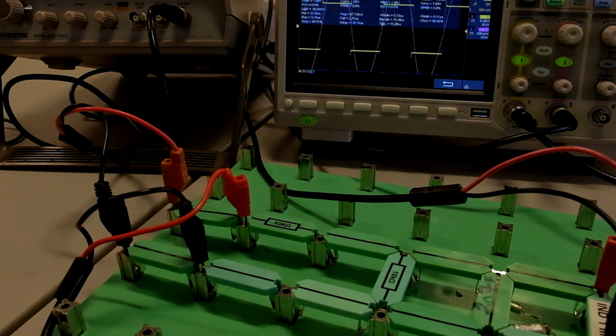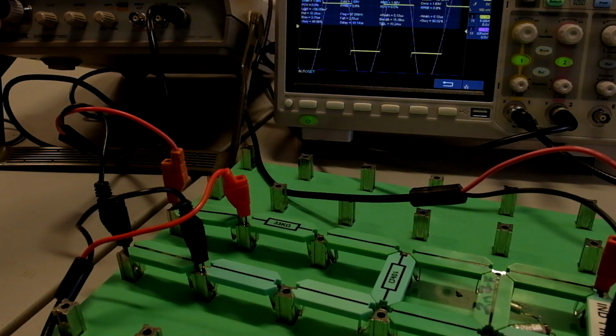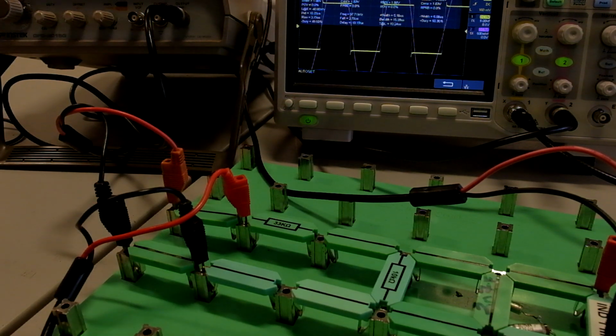So if we go to resonance, although we have a square wave going in, it filters out all the higher frequency components of that square wave, and we only get a sine wave coming out at resonance. If we go below resonance, again the output goes down and it's a bit distorted. Above resonance, again the output voltage comes down and it tends more at higher frequencies to a triangle wave. But at resonance you do get out just the base frequency, the base sine wave frequency. So it proves that it's a bandpass filter.